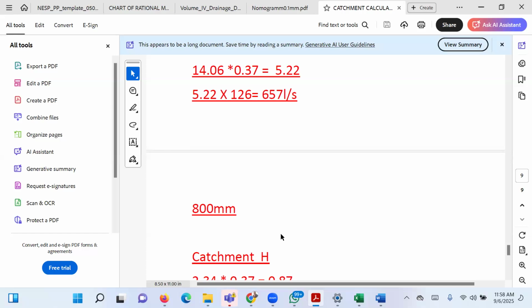So in this case, any value that is 700, we just use the nominal value of 800 mm pipe, 0.8 meter pipe. You see how we get nominal values? So once I do calculation and I get a value between 600 and 800, I'll just be using 800 mm pipe. That's why sometimes when I look at some designs by engineers, you see them using the same pipe size, and I'll just be laughing. Yes, you can use mostly nominal values, but in some critical areas, you can't just use nominal value. Especially if you're going towards the downstream, you must increase it.